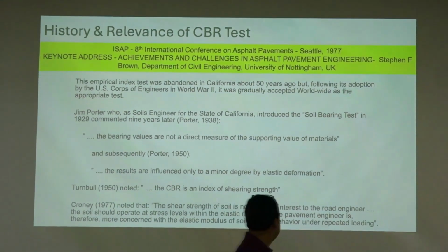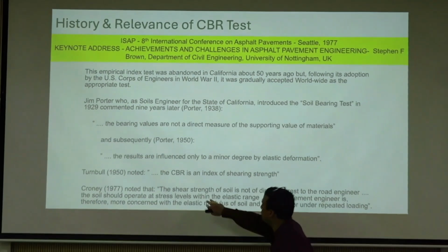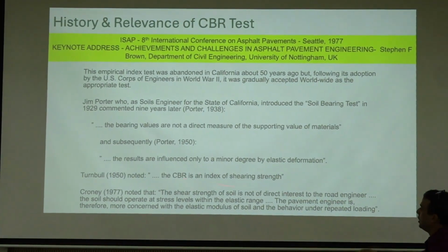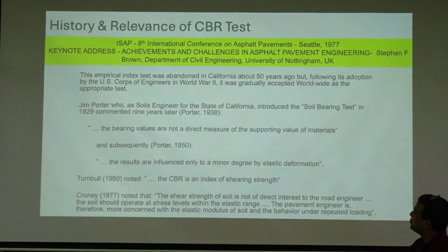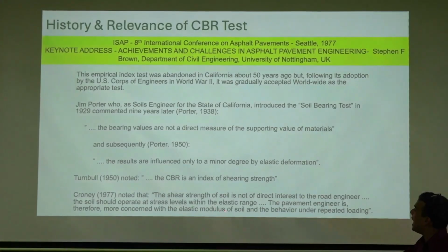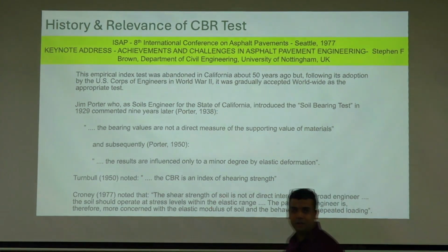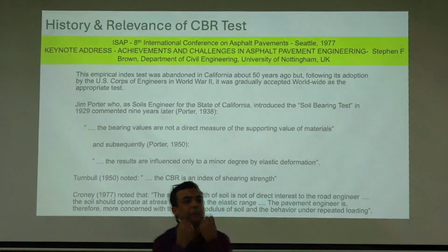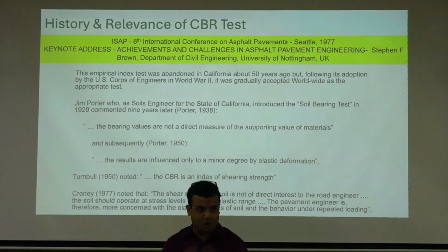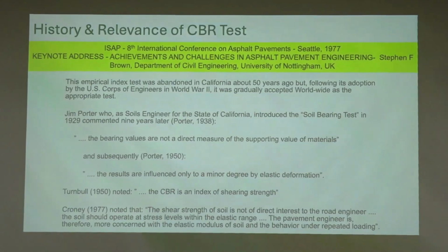So you'll have PDFs. So the point is CBR, and then in Croney 1977: the shear strength of a soil is not of direct interest to the road engineer. The soil should operate at stress levels within the elastic range. The pavement engineer is therefore more concerned with elastic modulus of the soil and the behavior under repeated loading, not under monotonic punching kind of loading, right? That's not how you're going to predict modulus.